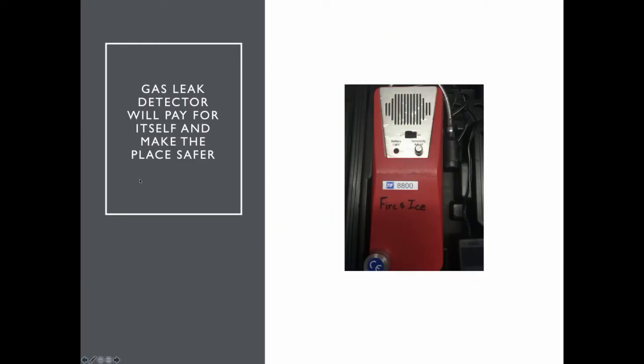A gas leak detector is a great investment. It'll pay for itself. If you go into a boiler room, and as part of your service, you use your gas leak detector to test the gas train, you can end up making it safer, because a lot of times you're going to find a gas leak in there. And you can talk with the owner about making it safer for them. And you can also take this into an elevator and start that ticking and get everybody scared inside here. It's kind of fun.